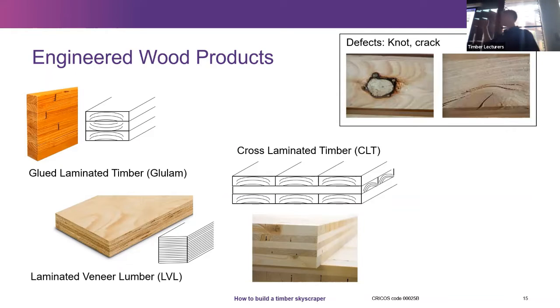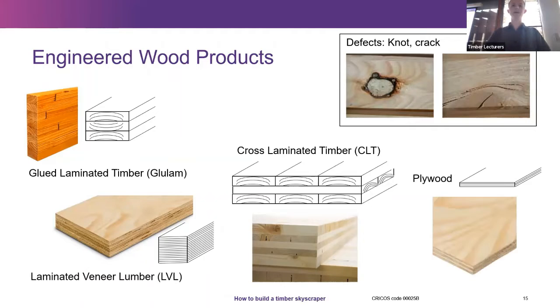And that last one has become really popular as an alternative to concrete slabs because it is made as really big slabs. They're about 4.5 meters wide and as long as 16 meters. And if you've biked around Kangaroo Point, probably a year ago or so, you would have seen a timber building with CLT going up. And it's called Monterey. Anyway, you can check it out. Look it up, Monterey, Kangaroo Point. It's a 10-story apartment building in Brisbane. I'll talk about it a little bit more.